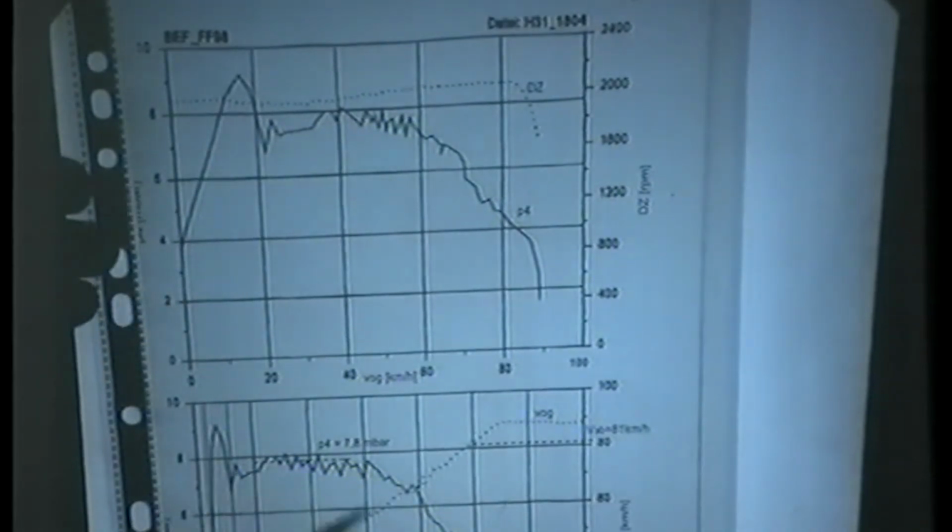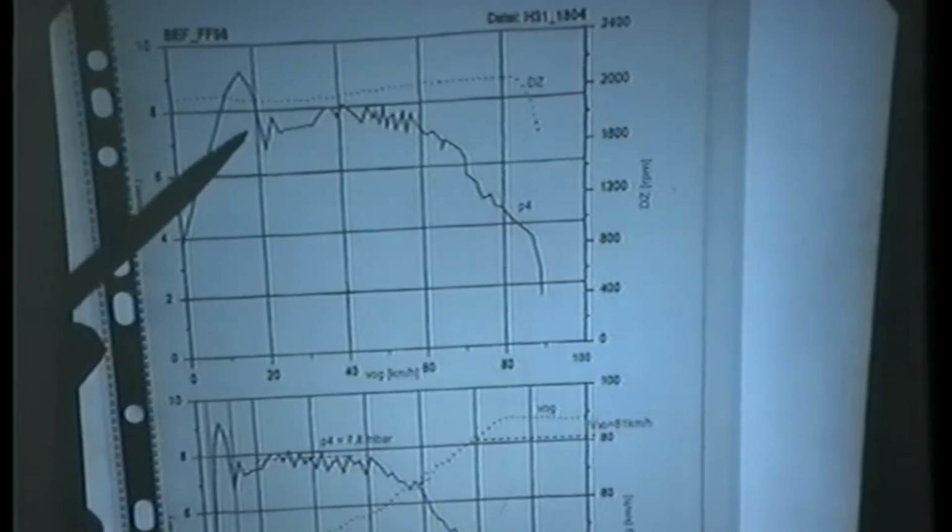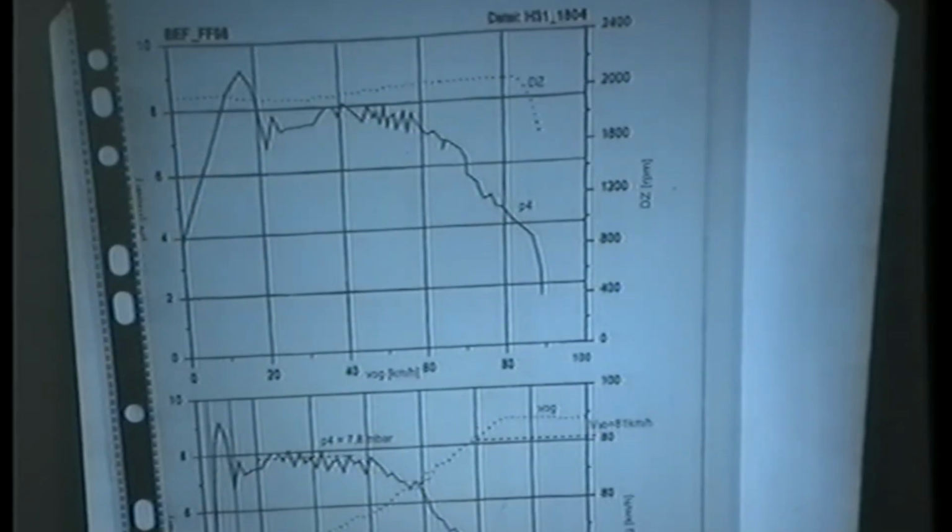And here, similar. So you see, in static conditions, we had a lot of pressure. And this is the pressure which is in the slipstream. This is roughly 110 kilograms per square meter pressure in the air. So multiplied with 6.5 square meters between the catamarans, this gives you 800 kilograms of lift. This is 80% of the craft, already in static conditions.